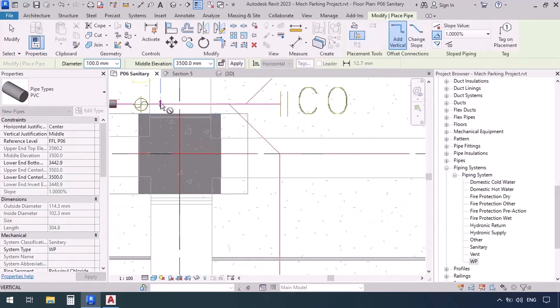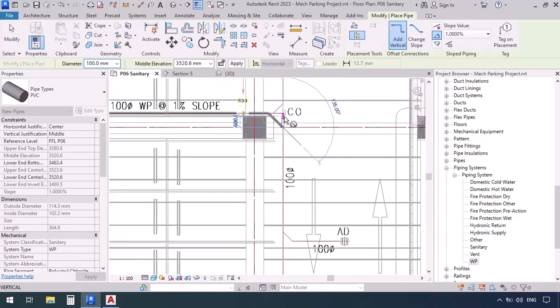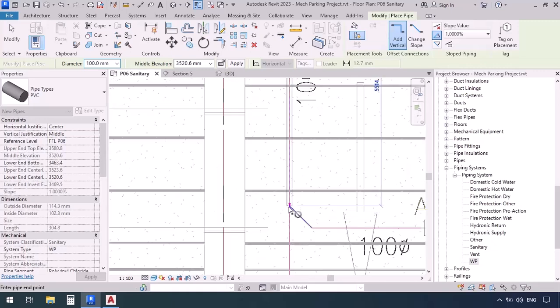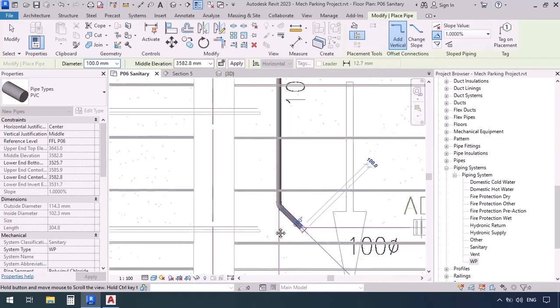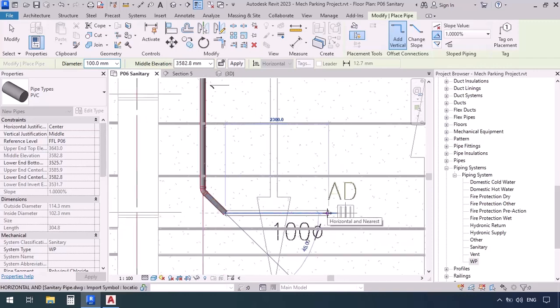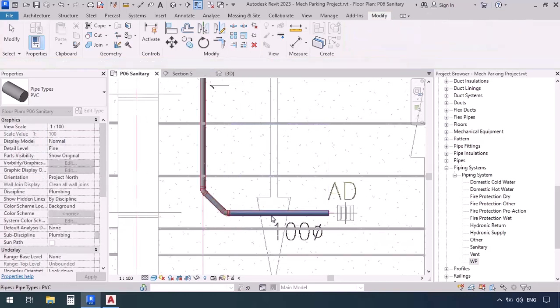So now I'm going to start here, click, then click again, then at a 45-degree angle, but maybe in your plan it doesn't say a 45-degree angle, which could be just a drawing mistake. But make sure to remember that you pay attention to drawing it at a 45-degree angle. Alright, now click, and click again, click, and then somewhere near the drain, the last click, then we press escape.